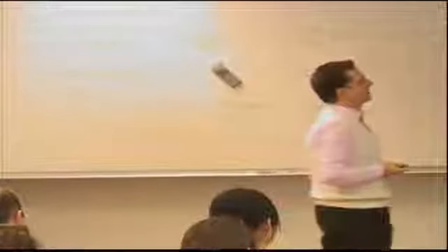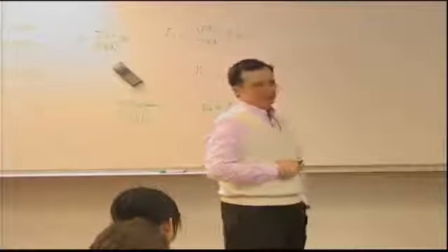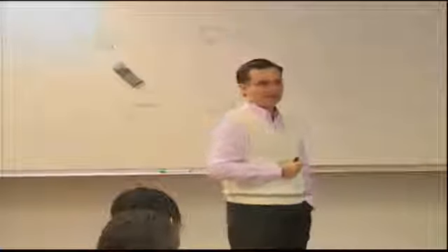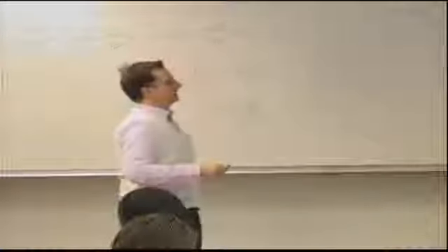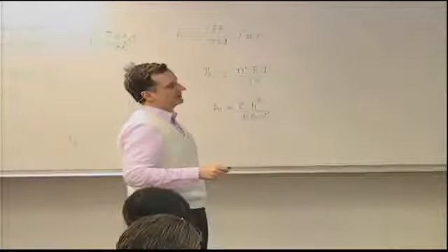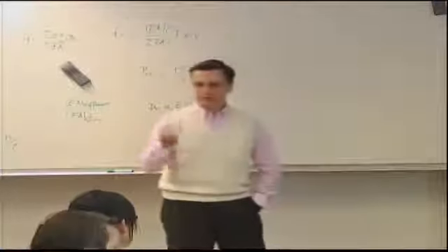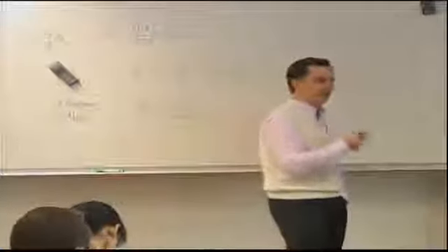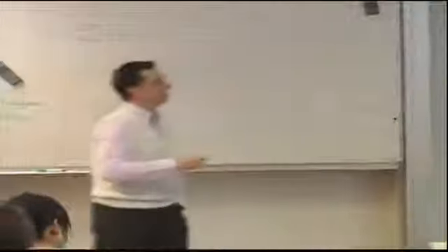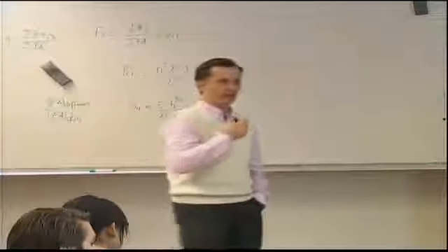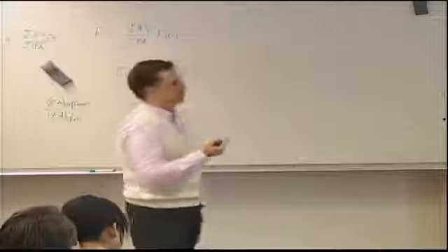So what does this mean in terms of typical values that one would get using this interrivet buckling calculation and the crippling? You'll see that it makes a big difference what type of flange stacking sequence or layup you use. Let's take a good stacking sequence and a bad stacking sequence for a flange. The good one will have a bunch of 45s, because 45s are good because of the D66 term present in the crippling equation, and therefore they will delay buckling. But it also needs a bunch of zeros so that the compression ultimate strength is as high as possible.